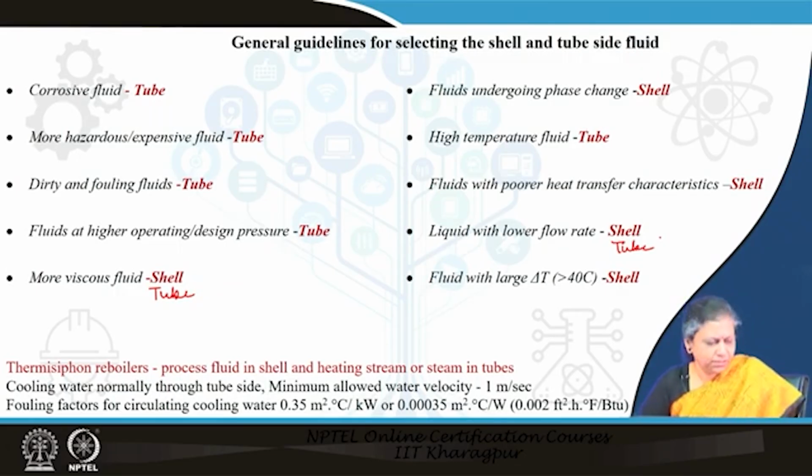It is quite natural, you know the logic behind it, since the most common use, or rather a very common use for shell and tube heat exchangers is in thermosiphon reboilers, where normally steam or any heating oil is used as the heating medium. And for the case of coolers, mostly we use cooling water. And the cooling water, you know why it is introduced through the tube side, because of its high fouling tendency.